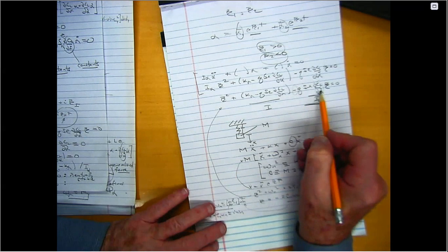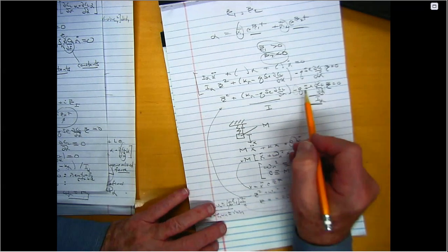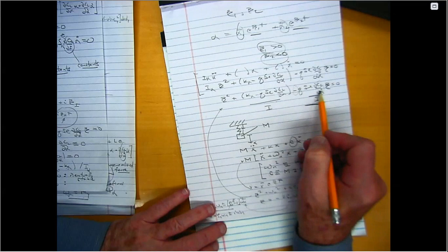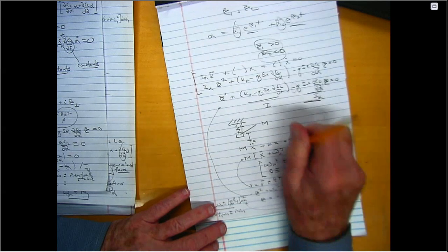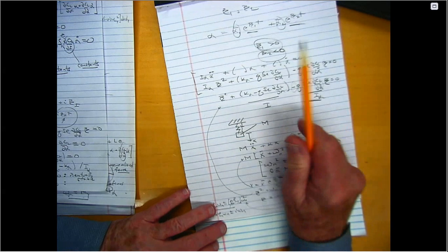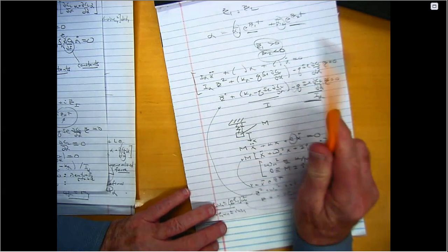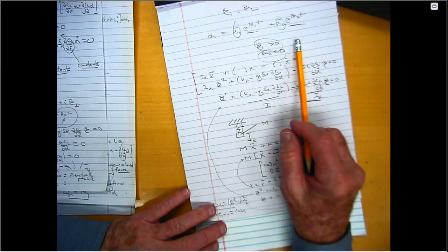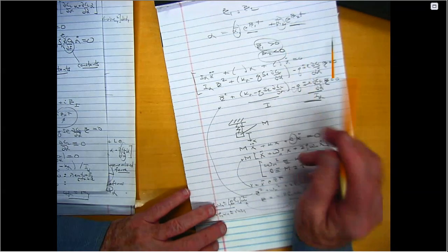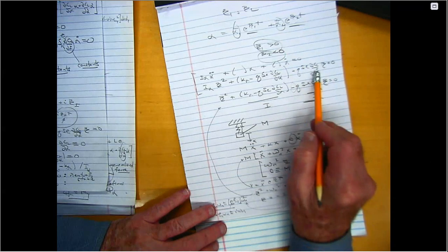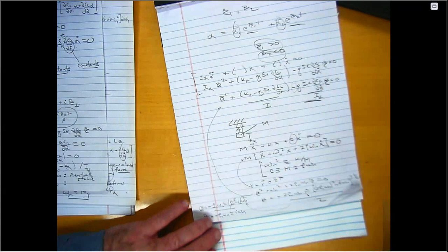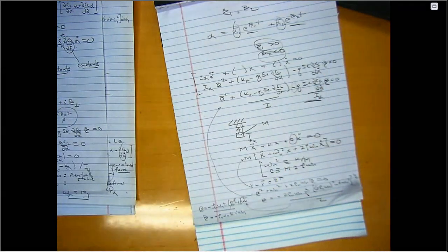A low Mach number is normally such that this is a negative number and it's positive damping. But if I get up into the transonic regime, that coefficient can easily be positive. And I can have negative aerodynamic damping, which means the system can be unstable just due to the negative aerodynamic damping. And there's a famous set of applications in the turbomachine where that happens. In fact, I'm told, most turbomachine flutter analysis is just about determining the sign of that term. And that's why you need to run the CFD code, just to find the sign of that term and how it varies with Mach number.